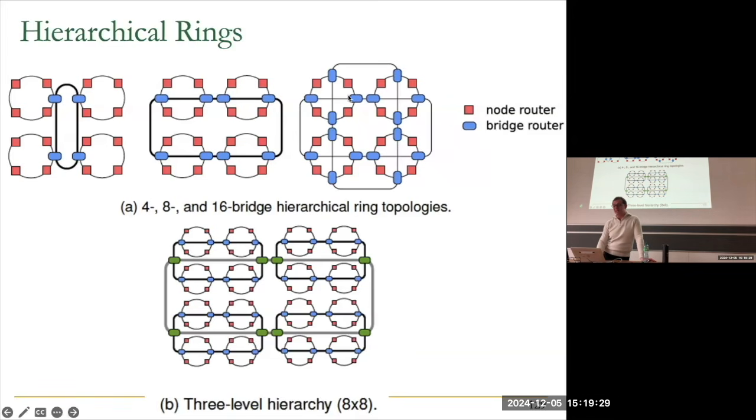You could do it if you have a bus-based partition, right? So hierarchy can be such that a collection of processors, let's say 16 of them, are connected via bus. You could do snooping-based coherence over there, but once you go out of that domain, you need to do directory-based. So yes, basically the answer to your question is yes. A lot of the existing protocols are directory-based protocols, even though there may be a bus-based or snooping-based component to it, it's restricted to a very small fraction of the chip. That's a very good question. So clearly there's a design or co-design of the coherence protocol and interconnect as well.